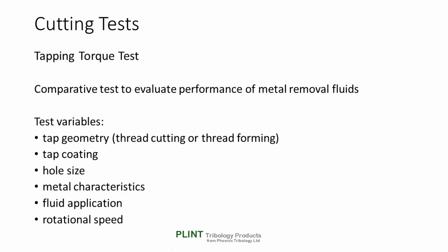The tapping torque test is one of the few bench scale tests that involves an actual cutting process. A tap is driven into a pre-drilled hole in a sample and the resulting torque measured. Results depend on the test fluid, the condition of the tool, the size and finish of the pre-drilled hole, and the workpiece material.